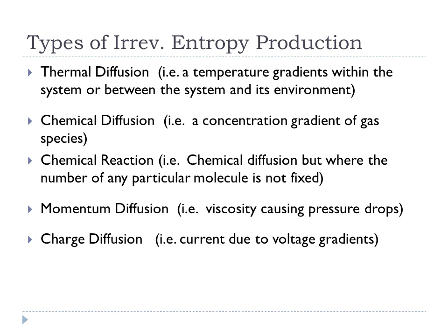You may need to supply a pressure gradient to overcome the viscosity. The reason is that you have something called momentum diffusion: at the walls of the tube, the gas or liquid can't have any velocity, but in the center it's going to have a velocity, and because of that you have a gradient in the velocity, which is effectively a gradient in the momentum.